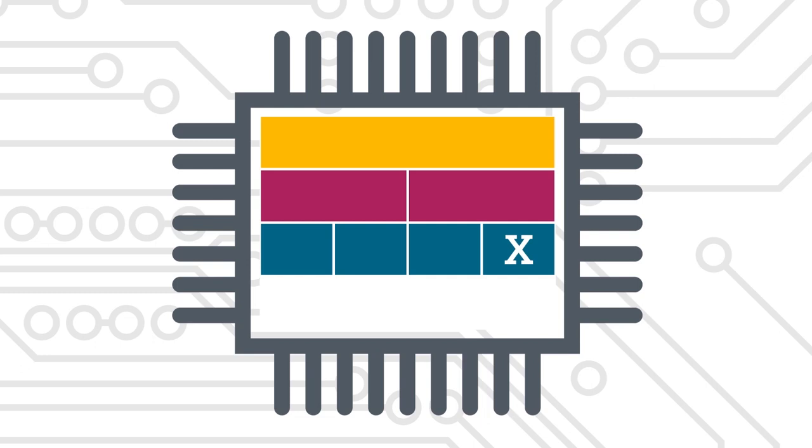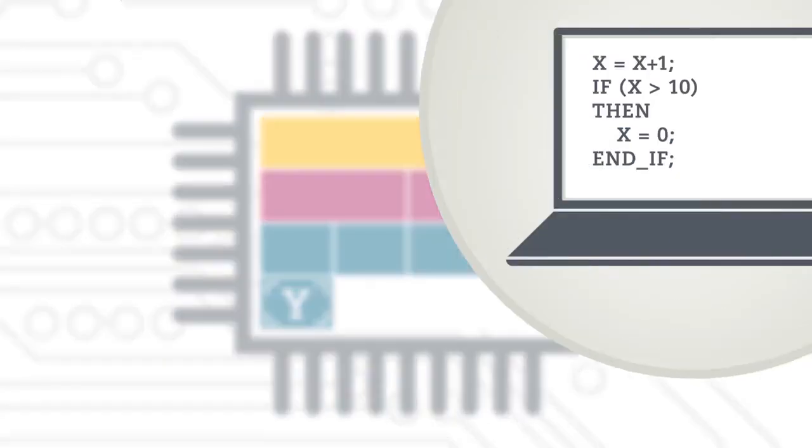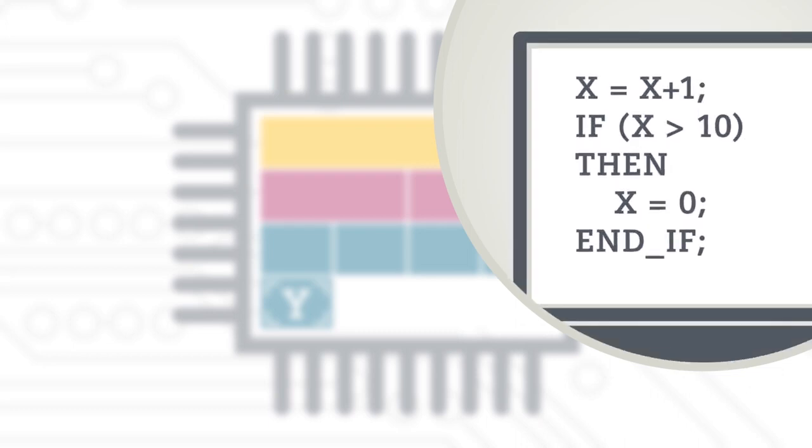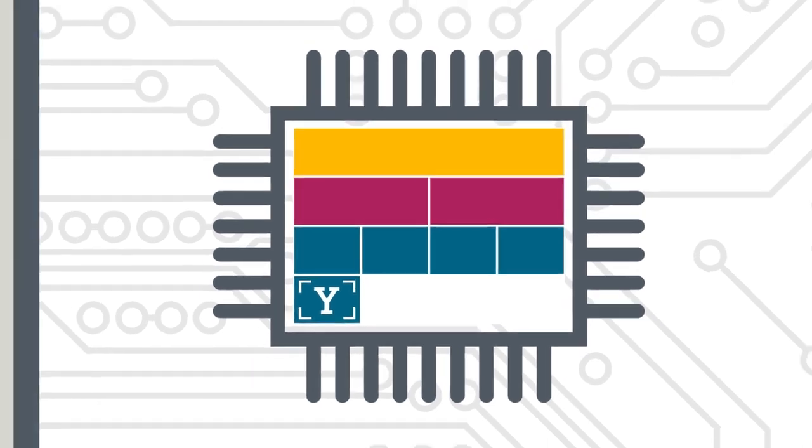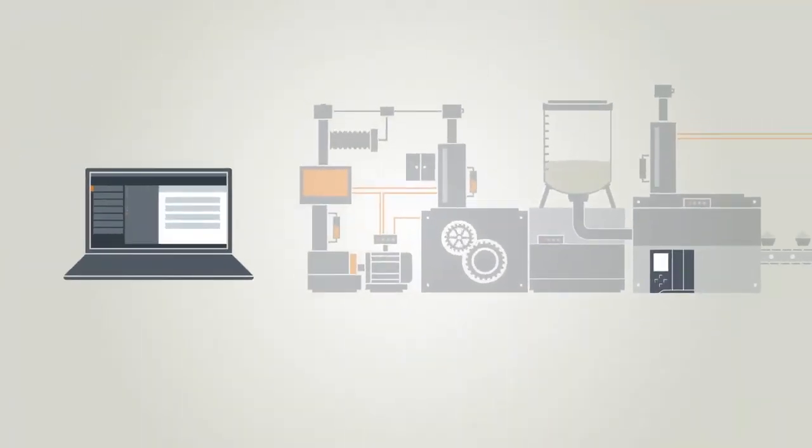During programming, tags are no longer addressed absolutely, but symbolically. The TIA Portal monitors the assignment of the symbol to its memory address. In other words, the change of an address or tag name triggers an automatic change of all use instances as well. How does that look in the TIA Portal?